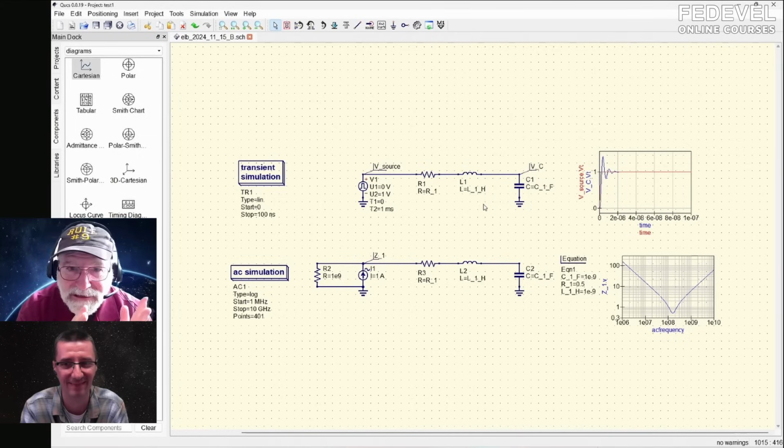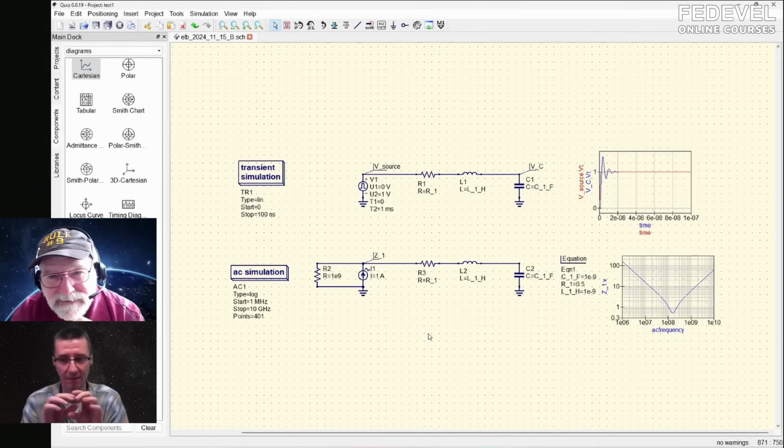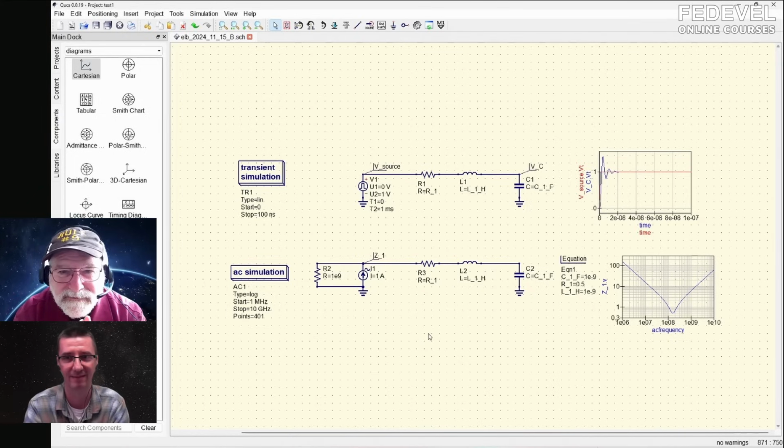And there's a connection: if I know the impedance and time delay, I can tell you what the L and the C values are. In fact, we're going to do that. But the LC thinking is an approximation, whereas the transmission line is also an approximation, but a much higher bandwidth approximation. Okay, so let's explain what's the difference. So a transmission line means it's many capacitors and inductors in series.